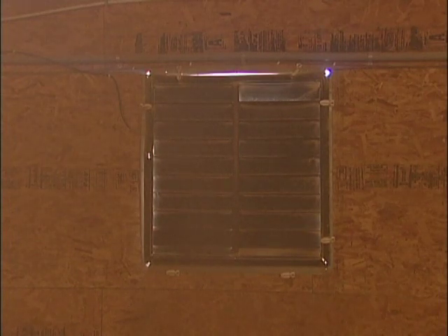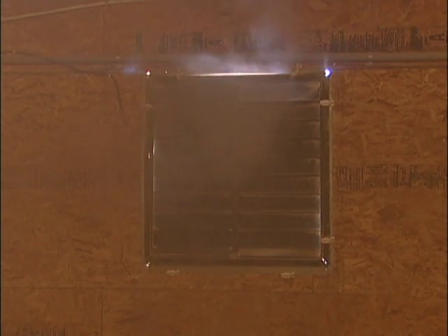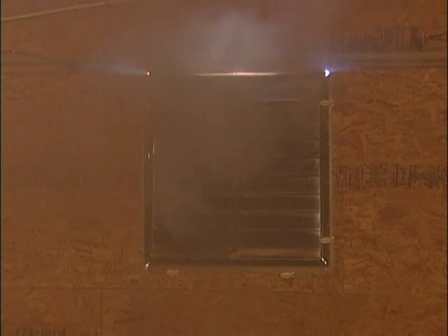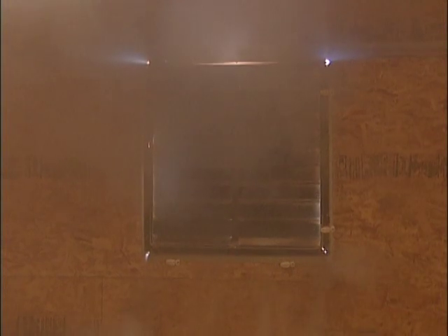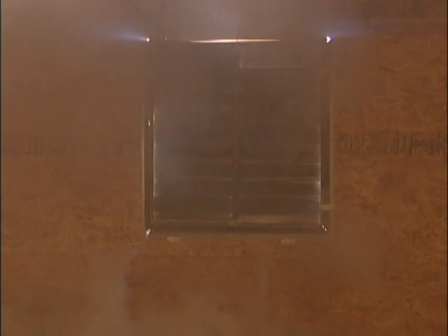What we're looking at here is a minimum ventilation shutter on a sidewall fan. And if you see at the top, they tightened the fan housing too much, so we have a big gap that leaks at the top. And the main place we don't want it to leak is at the bottom of the shutter, so the cold air entering when the fan's off doesn't go directly to the floor.